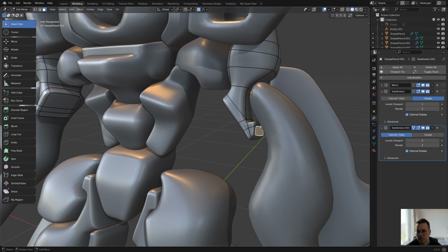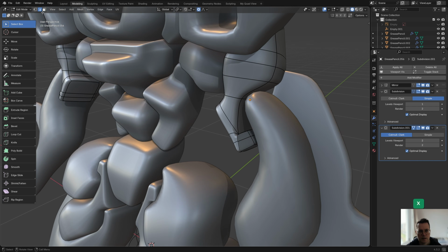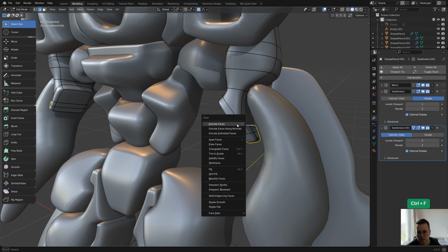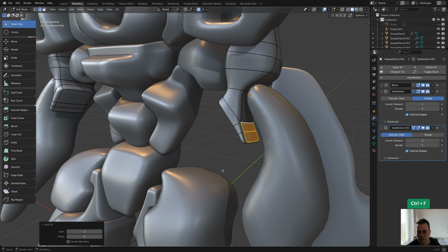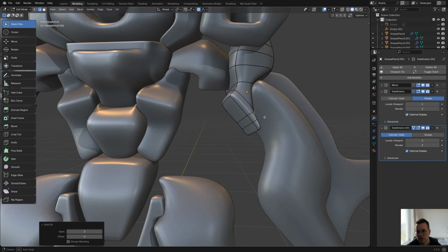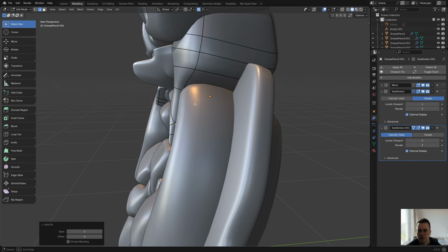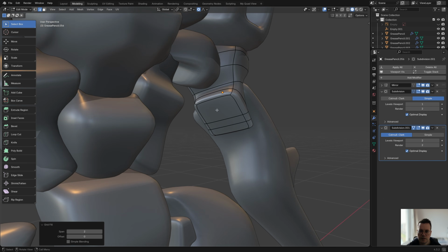And let's see, we can also just select these two faces and press Ctrl and plus, and then just delete them. So X and faces. And then in edge selection mode, just Alt and left click on this and press Ctrl F and then choose grid fill, or alternatively go to face and grid fill, just so that that is filled again. And in this case, I want this shape to be a bit rounder. And what I'm going to do is just add a loop here.